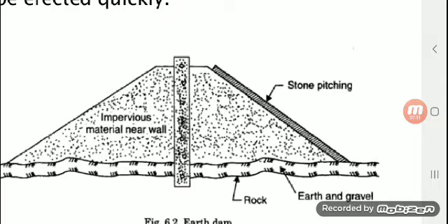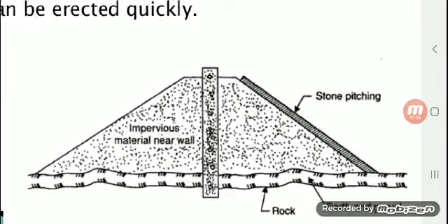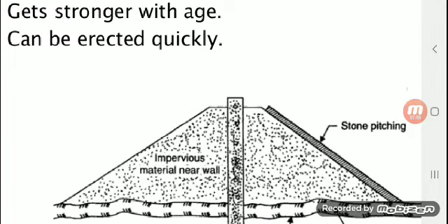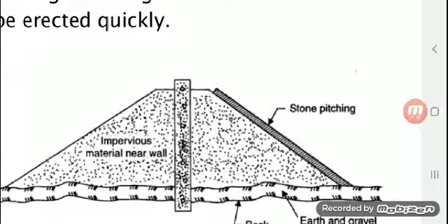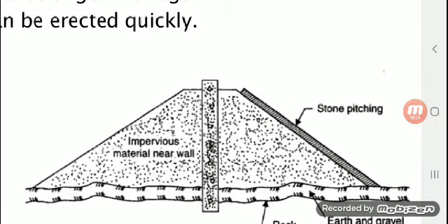in this triangular structure we have filled impervious material, which will not allow the water to pass through it. So small stony materials, or some sand, or small concrete, some small rocky formations will be used here. This type of structure will help to stop the water when the river flow is very low, or we can use this type of structure on canals